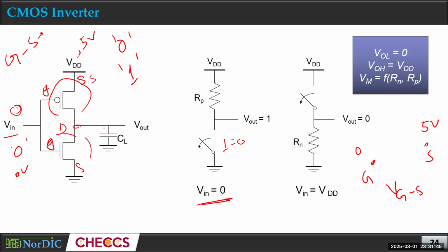When we get the voltage between two nodes, the gate is first, so we always have this relation: gate voltage minus source voltage. Here we have negative 5. But if we calculate the source to gate voltage, we have positive 5. The node that comes first is the first, and the second node is subtracted from it. That's the way we calculate the voltage difference between two nodes. I think you know that.